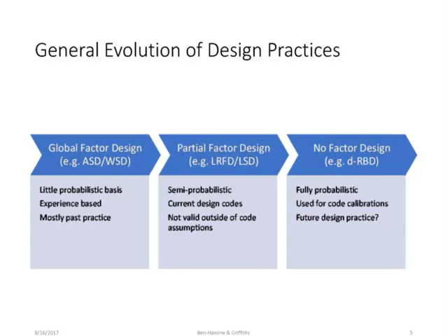So the standards, when they specify all these load factors and resistance factors, are targeting a certain reliability in the design. So it is probabilistic in that sense, but it is still called semi-probabilistic because if your design is outside those assumptions, then you cannot say that you achieved the target reliability for that design. So you will have to do additional studies.